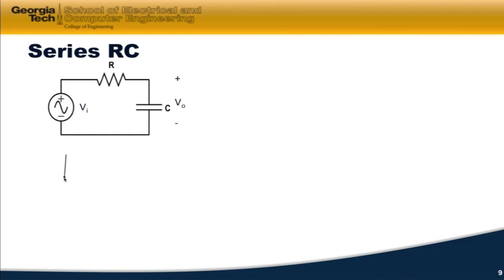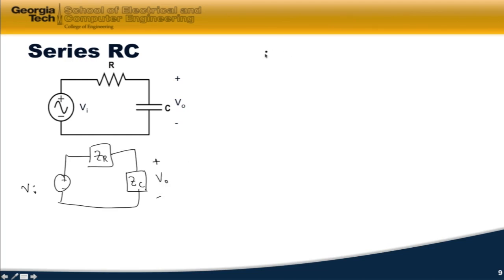The first thing I'm going to do is replace this circuit with impedances, Z sub R and Z sub C representing the capacitance. I've got my input voltage and my output voltage. I'm going to use the voltage divider law here. The voltage divider law says that V out is equal to Z sub C over Z sub R plus Z sub C times the input.